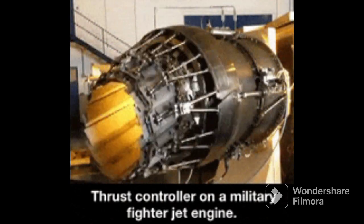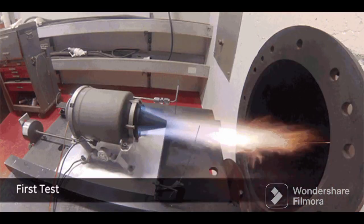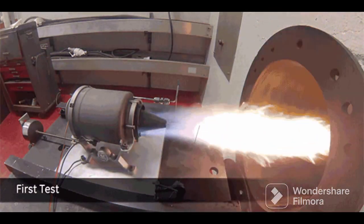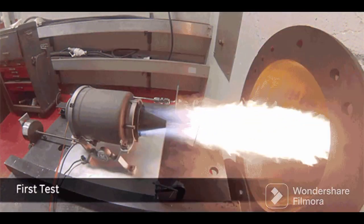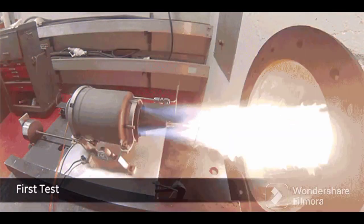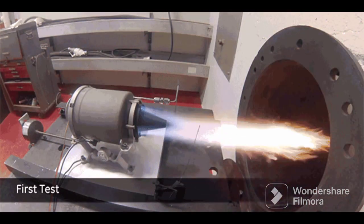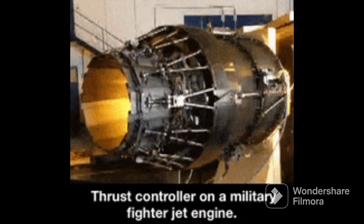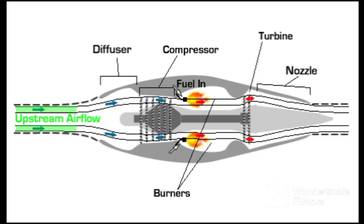The nozzle of a jet engine is responsible for accelerating the high-temperature, high-pressure gases produced by the combustion process and directing them out of the engine to produce thrust. The exhaust nozzle is typically located at the rear of the engine and is designed to control the flow of the exhaust gases and increase the velocity of the gases as they exit the engine.